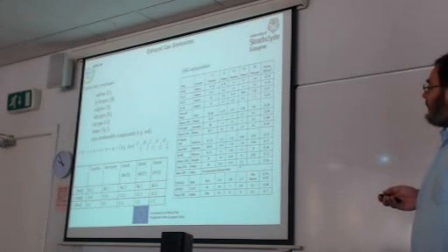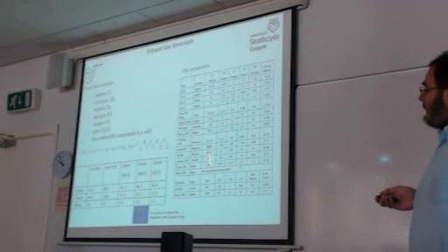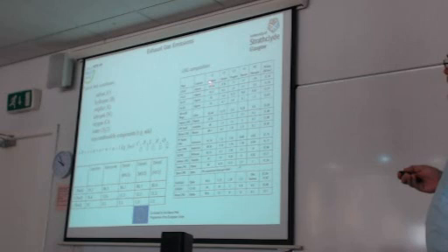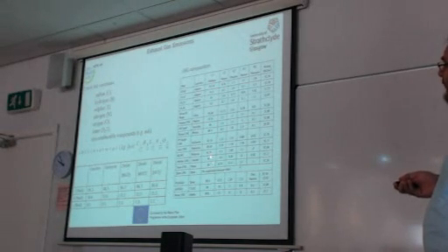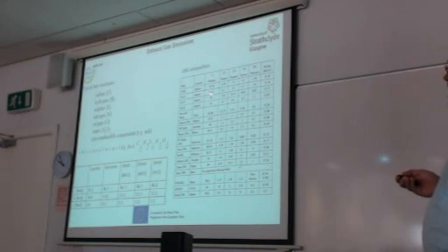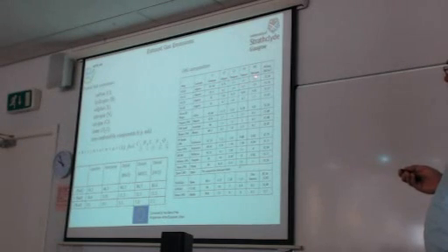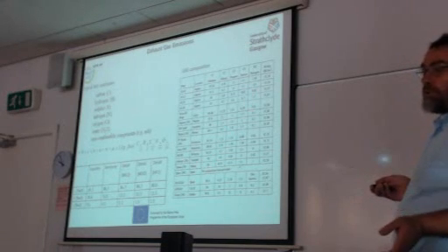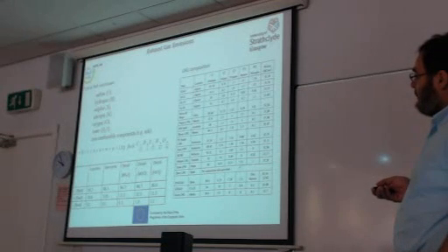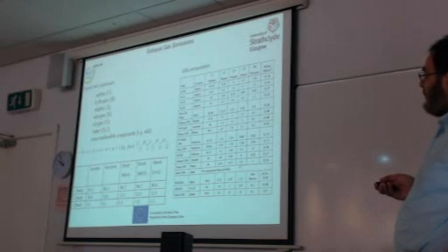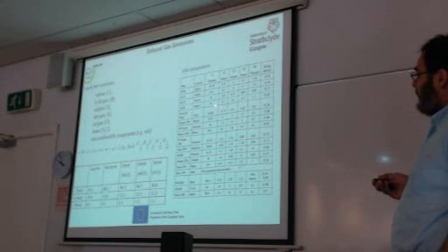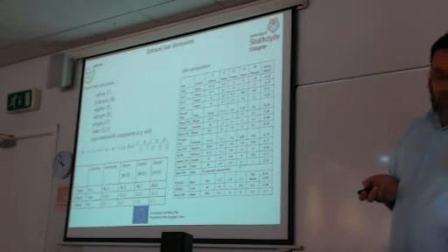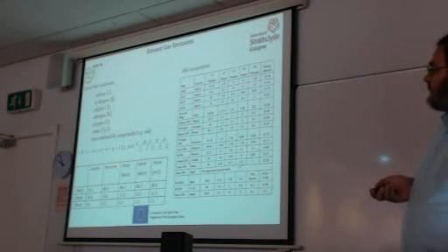And if we see the LNG composition, of course, LNG composition varies depending on the geographical area where the natural gas is produced. But the main constituent of LNG is methane. And actually, methane composition varies from 87 to 95%. And then, apart from methane, we will find in LNG ethane and propane, butane, and nitrogen. During the liquefaction process, nitrogen is totally removed, because the liquefaction temperature is different in natural gas and nitrogen. So LNG does not contain nitrogen or contains only a tiny small amount of nitrogen.